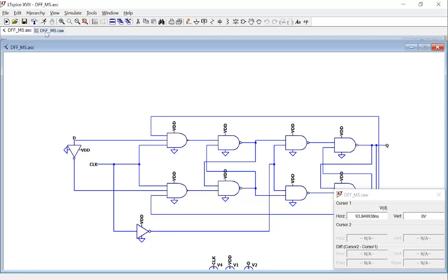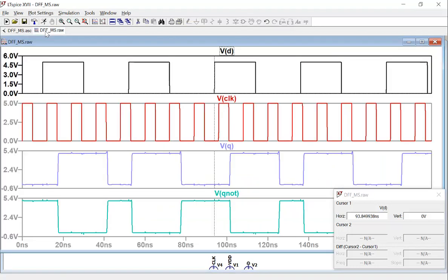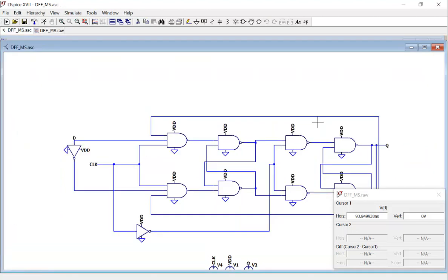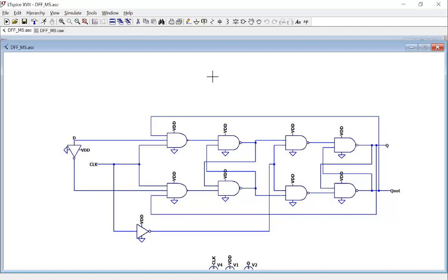So this is called an asynchronous D flip-flop, which is fine. I mean, it has its pros and cons compared to the synchronous D flip-flop, but the major issue of this structure, in a lot of places you will see this structure in the textbook, but it doesn't have set and reset functionality with it. So for our ADC, you cannot use this structure. It's very difficult to add a set and reset. You can only set it or only reset it, but if you want to do both set and reset, it's just impossible. Okay?